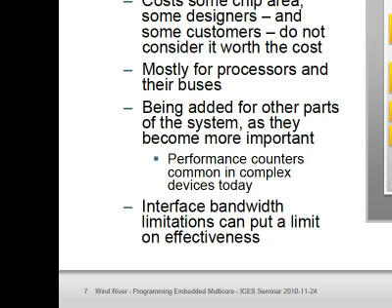One way to debug a multi-core system is on-chip trace. This is to add actual hardware onto a multi-core system to specifically collect the execution traces of different cores within the same processor. It can capture the addresses these cores issued and also the instructions these cores executed. Performance counters can also be added to trace the execution performance of these different cores.